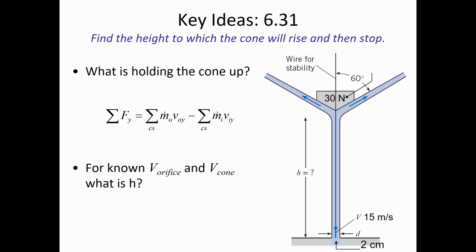So now think about the velocity out versus the velocity in. The velocity in here is all vertical. The velocity out, even if the speed doesn't change, the direction of the velocity vector does. And so you're going to have to take that 60-degree angle into account, where only a portion of that exiting jet is in the vertical direction.